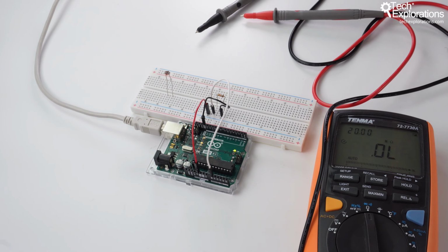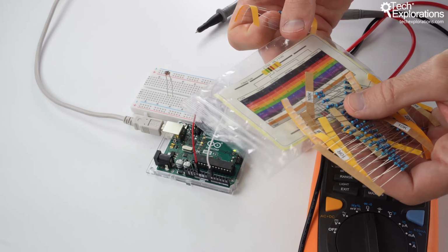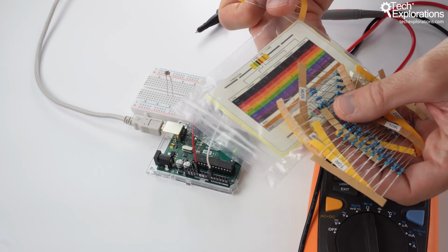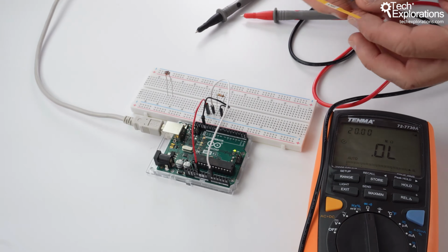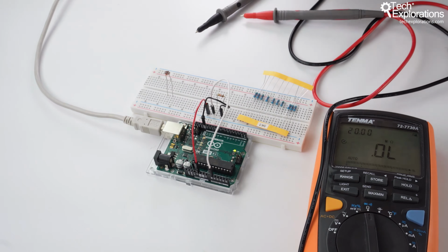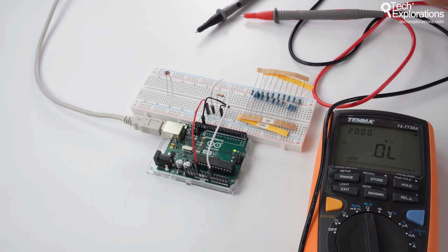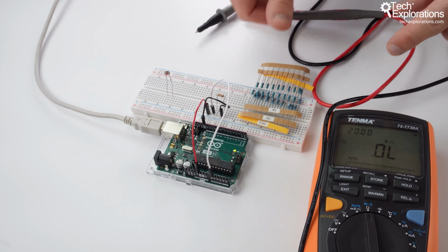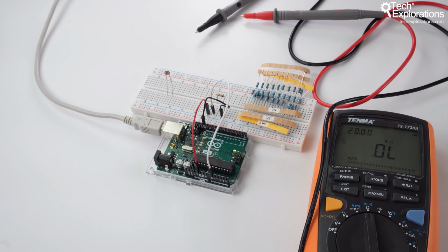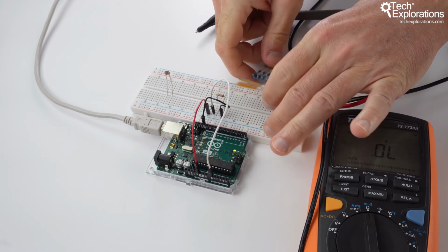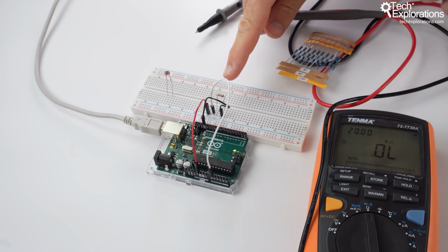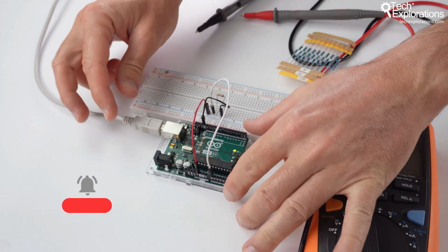And I think using the resistor pack that comes with the 3-in-1 kit from Sunfounder, I think I can put together one of those resistors. A 5.1, let's say 5. Another one of the 2 kilo ohm resistors, and another one of the 1 kilo ohm resistors, and that will give me close to 8.64. It's probably going to be around 8.1 kilo ohms, but it's closer to the value that I need compared to the 10 kilo ohm resistor.